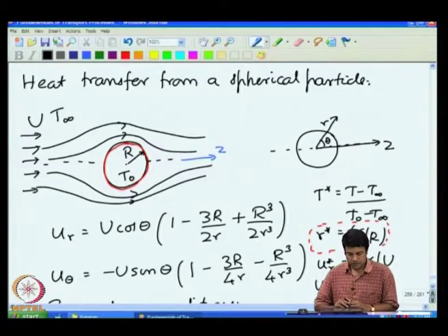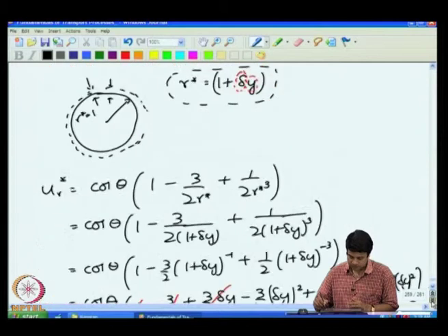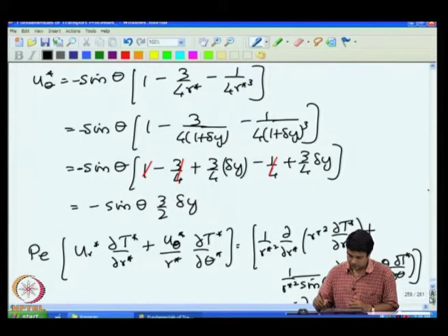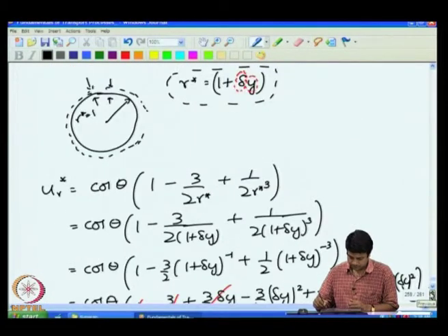Since the temperature far upstream is T infinity and there is no variation in temperature along streamlines, that means that the temperature everywhere along the streamlines has to be T infinity. So, there is no variation anywhere in the temperature. Okay. So, that is the result that you get just by neglecting the diffusion terms altogether in the limit of high Peclet number. Okay.